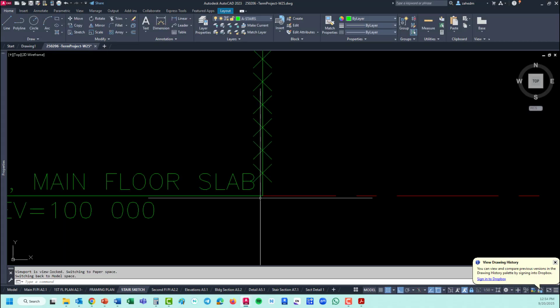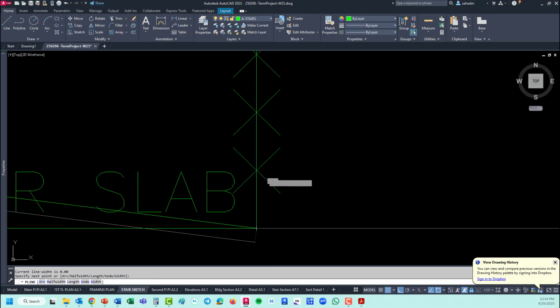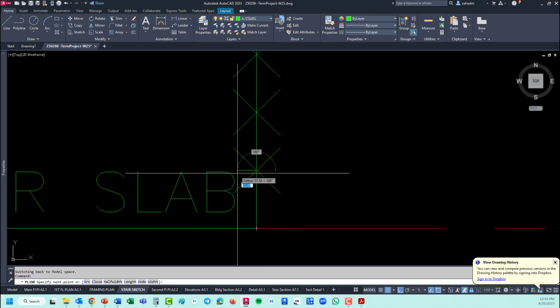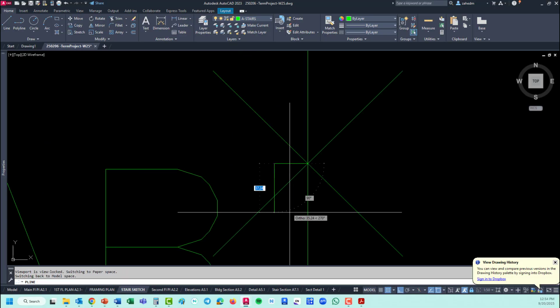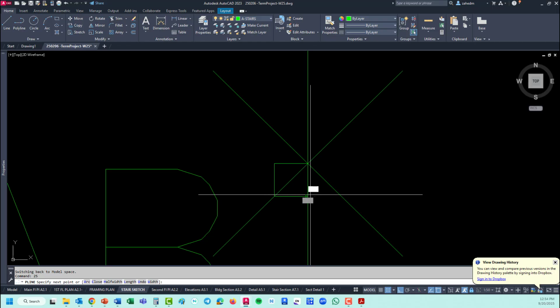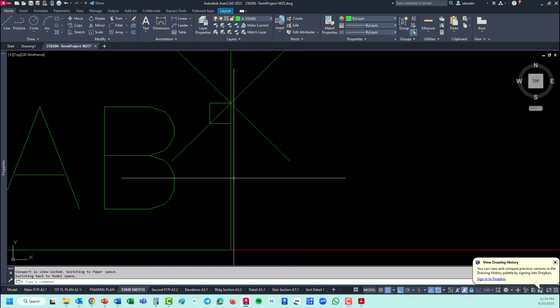And then we need to have a polyline from here, go up 25 millimeters, out for 1 inch nosing, 25 millimeters down for the nosing, and then close it. So this little piece right there provides me with the guideline to how to create my first step.